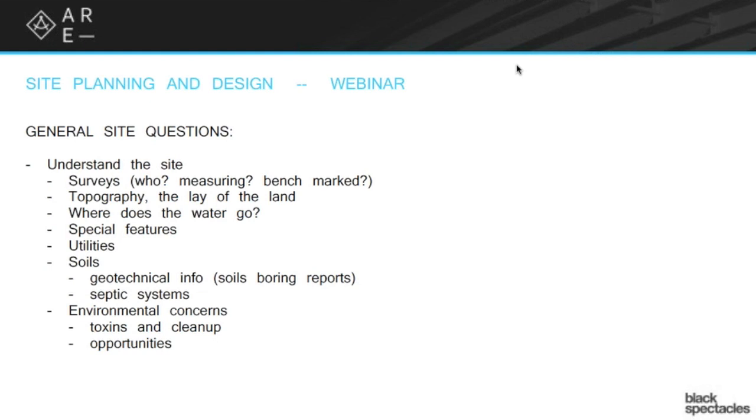Well, if I'm going to use a septic system and the only place to do that is at a higher elevation than where I want to put the structure, then that septic system is going to leach right into my basement. Well, that's no good, right? So understanding the utilities is, in fact, understanding site planning. Right? It's a huge part of it. You cannot forget those. It's easy to imagine questions that could show up about utilities.